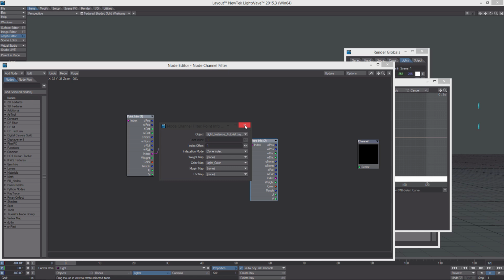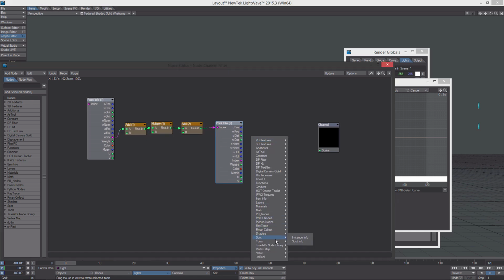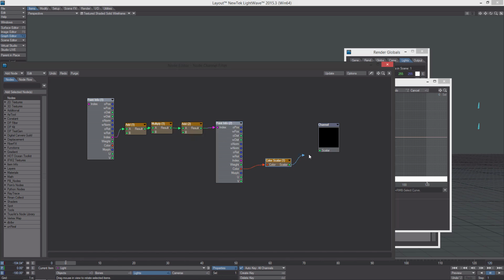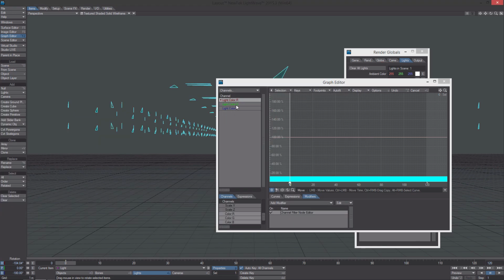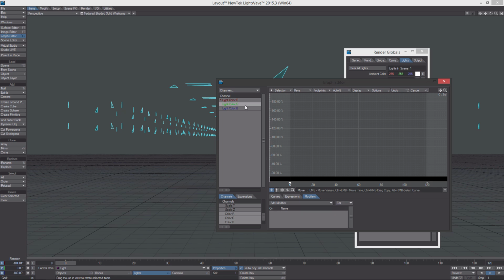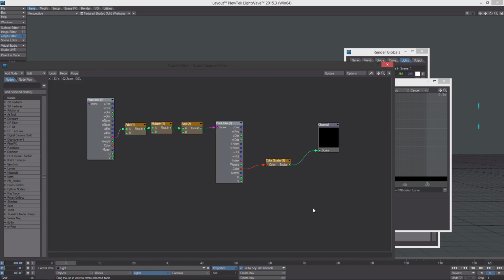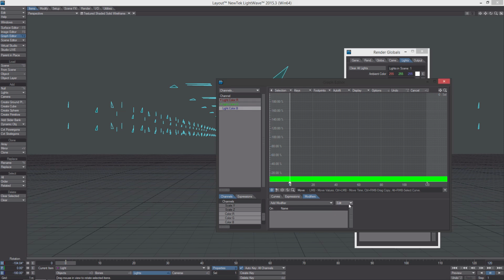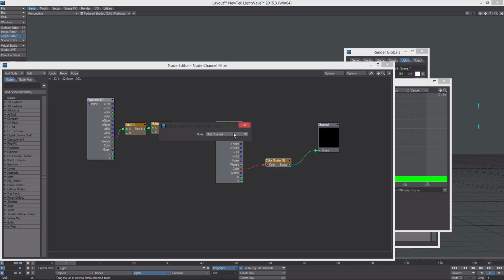And then I'm going to select the color map from the first point of each triangle, and then we're going to get a tools color scaler, and we're just going to break out the red channel. So now if we do that on the other 2 channels, I'm just going to clone them on there. I just deleted the keys, so there's no keys. Pasted it in the green. We're going to switch it to green. Pasted it in the blue. Switch it to blue. So that takes care of the color.